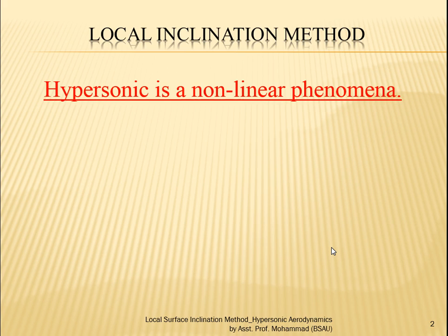And this is a normal concept, which we will not have any difficulty in accepting, because we know that hypersonic involves a lot of uncommon phenomena, like high temperature chemical reacting flows, viscous interactions, and thin shock layer phenomena. So all these give a clear idea that what is going on here is not linear. And if it is not linear, it's not simple. It's not simple to study, analyze, and put the input into an equation.